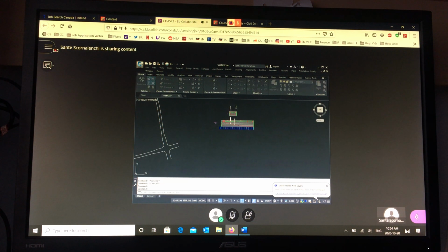It's the cul-de-sac now. I'm going to see the existing road, add it. You can add the proposed road too. I'll demonstrate that later because that's how the PDF shows it, but I just need the existing ground. I've added it. I'm going to change the style right here so that it looks red dashed. I want to see existing ground red dashed.